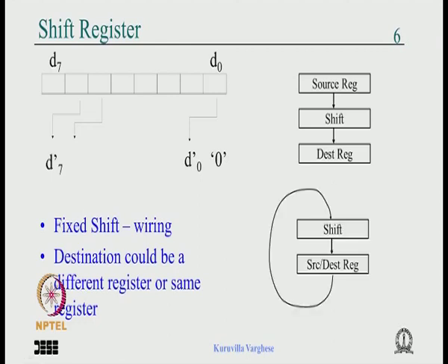only in very few cases is the destination the same as the source, because you have a data path where the data goes through a pipeline. So there is no way you can push it back many a time, so it goes all the way, unless the algorithm itself has an iteration back, then you iterate over the data path. The example will be some kind of encryption schemes where you iterate over, which can be unfolded, but that's a very costly operation, so it is iterated back through the data path.